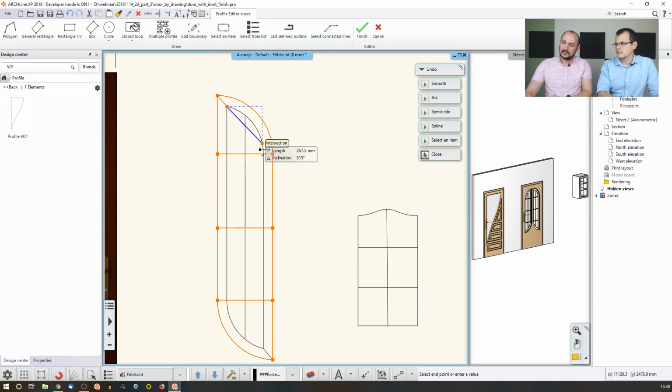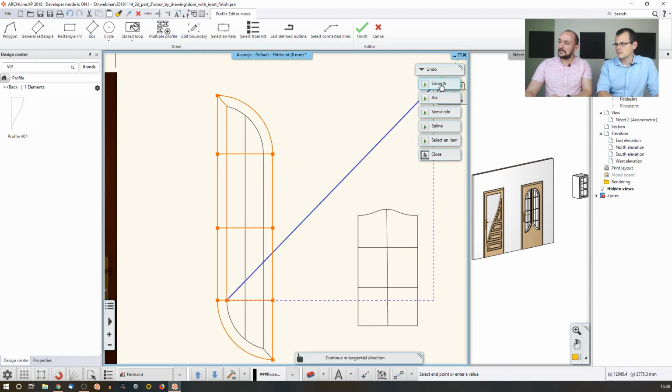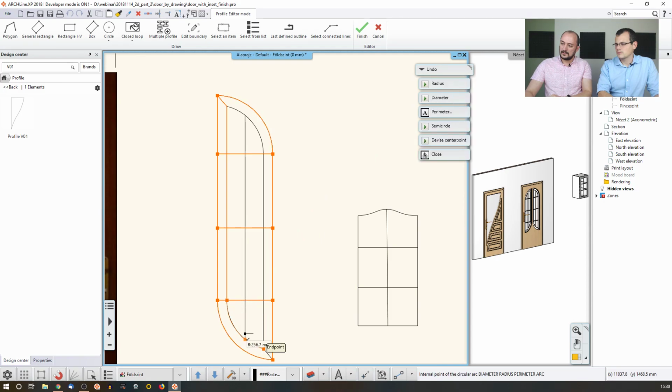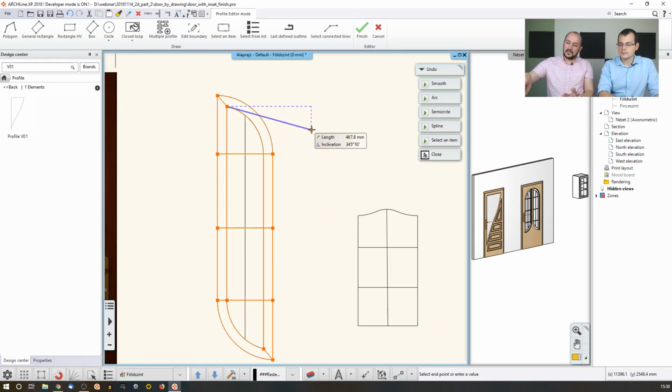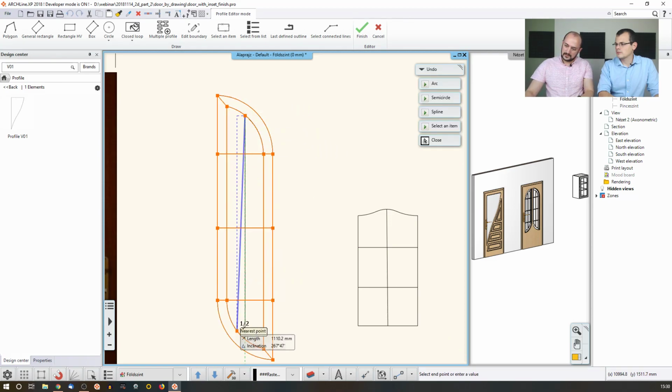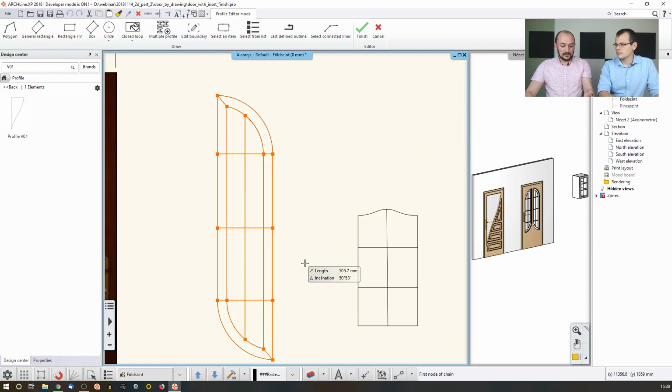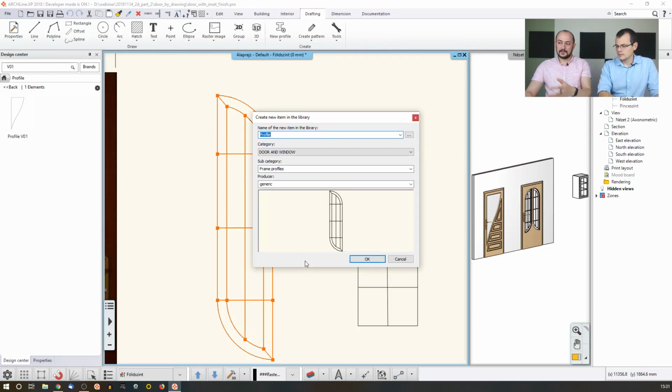So if I go here, click, click, and say, okay, this is an arc. This is kind of a half profile, and then I just start from here and do the other way around. Arc. The whole point is that they must be created in one single step. These are several corner points, but it's one edge, another, and one vertical. So this is how you do that. This is the final one. And then when you are finished, you just hit enter, and the software understands we are done.